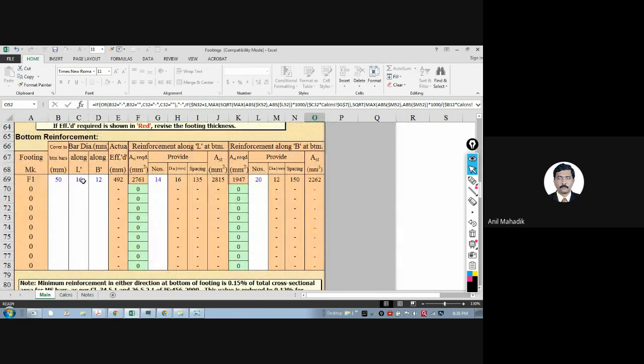Now you put the steel here. You can assume this as any diameter. अभी ये करो. So as we have already discussed that if the spacing is less than 100, try to increase the diameter. Yes sir. Okay, so increase the diameter and then again reduce the steel. Start with some number. 15 is okay, 12 is not okay, 13 is not okay, 14. So 14, you just do the trials from minimum to maximum till it gets satisfied.